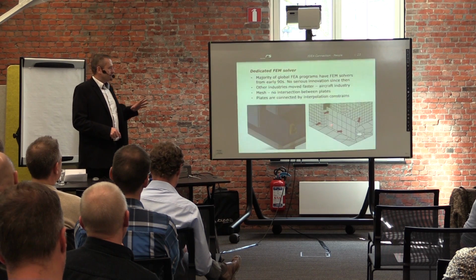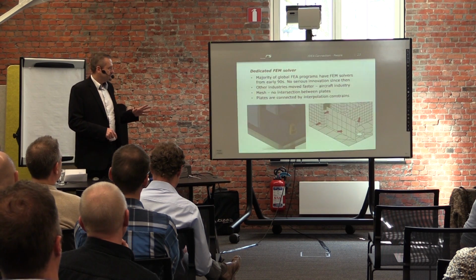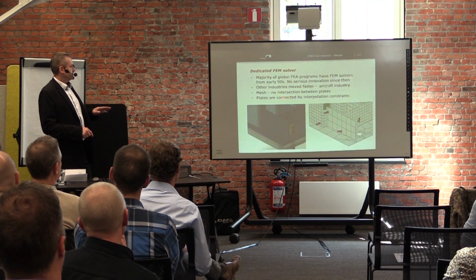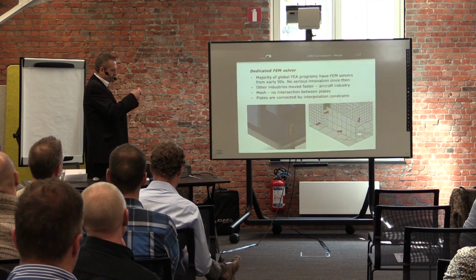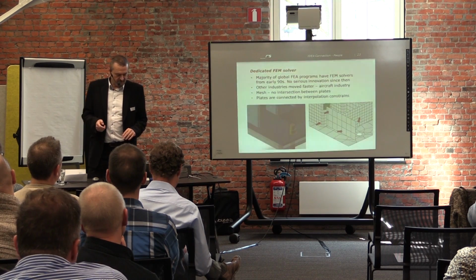And all connectors which we have in the connection, they are mostly welds and bolts. All these connectors are modeled with special interpolation constraints. You can imagine small beams there, but they are not beams. It is really a force interpolation constraint. And with these things we are able to connect properly these separate elements.